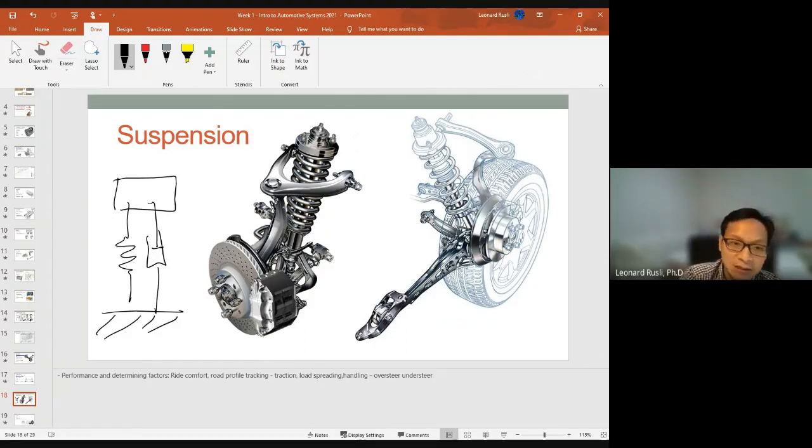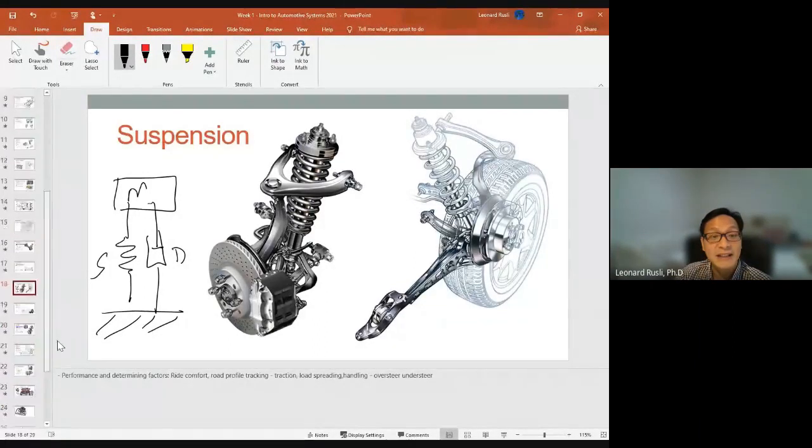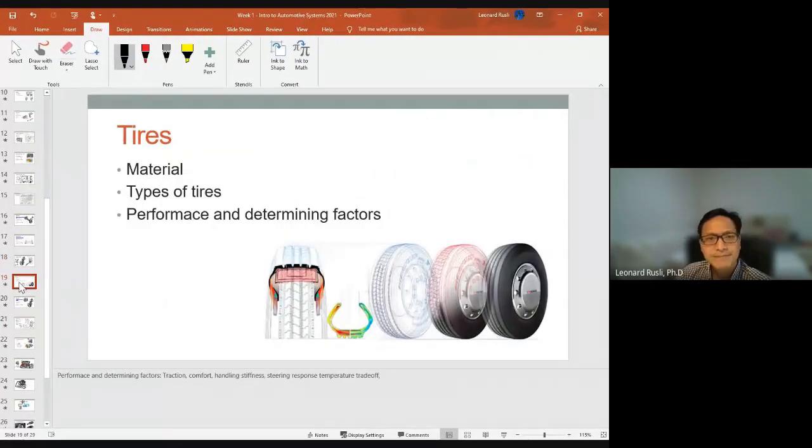Okay, so this is a mass spring damper system. Mass, spring, and damper. The damper is to get rid of the energy. The spring is to bounce it back to the original and to absorb energy, also some, not much. If you have the spring without the damper, your car will be endlessly bouncing, right? The damper is there to kind of stop the bouncing. This is a second order system if you study it in applied math with Bu Yunita.